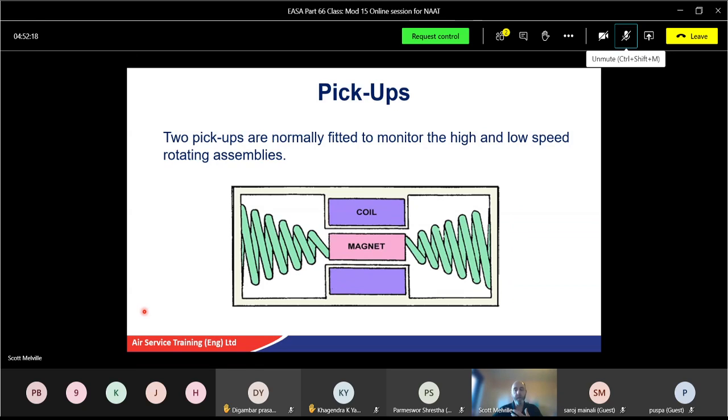So as the engine vibrates, the pickup body and the coil will move, and due to inertia, the magnet tends to stay in its original place in space. The resulting movement of the sensing coil will therefore produce an EMF in the coil, and the magnitude of the EMF will depend on the vibrating force, and the frequency will depend on the rate of vibration. So you've got springs in there, the magnet will stay there, so as it's vibrating, that will induce an EMF.